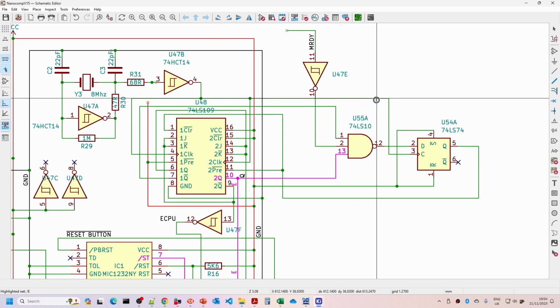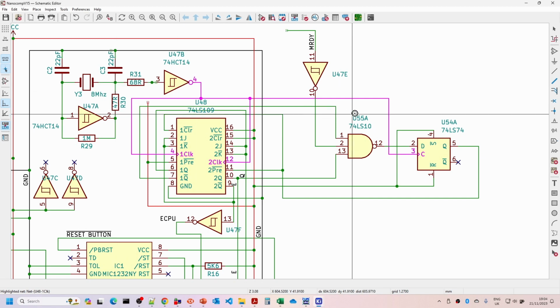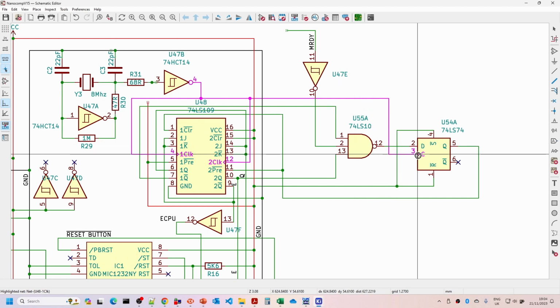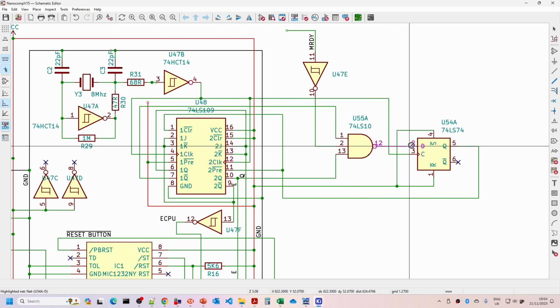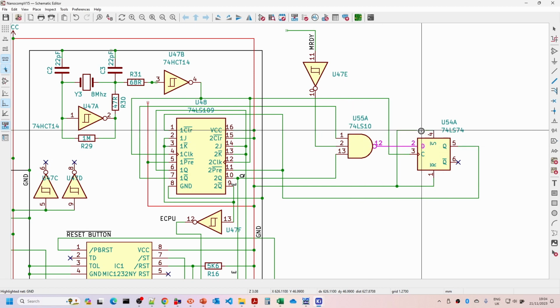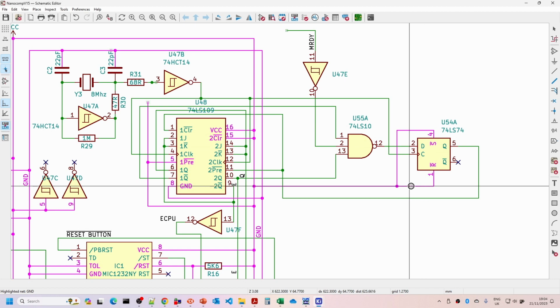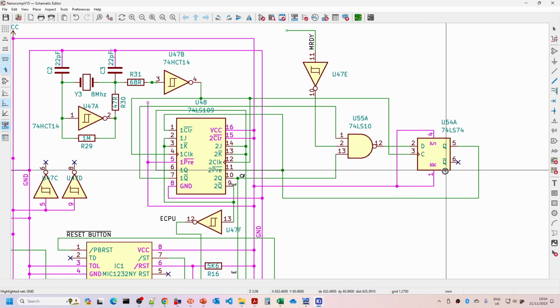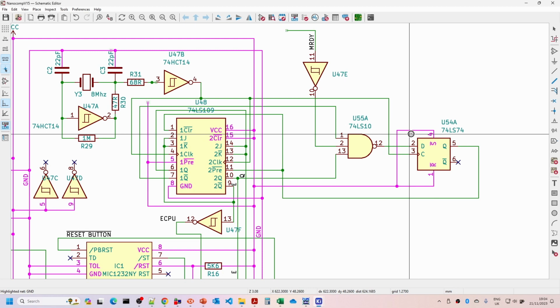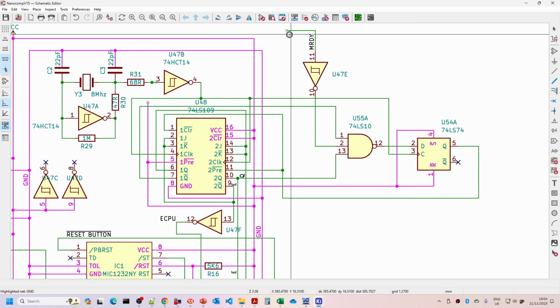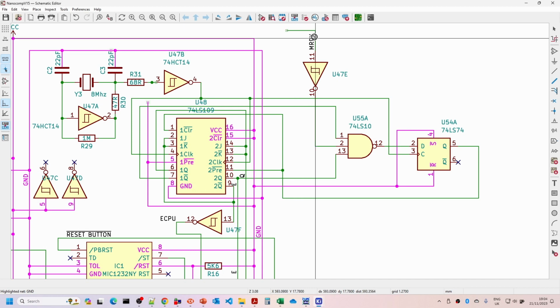And then we have a feed of the 8 MHz CPU clock going into the clock, and the output here goes into the D latch input, and then the set and preset are both set to 5 volts, to high. So hopefully this should be relatively straightforward to hook up. What I'm going to do to start with is wire MRDY to 5 volts, so everything should carry on as if nothing else has happened. It should be unaffected by that situation.